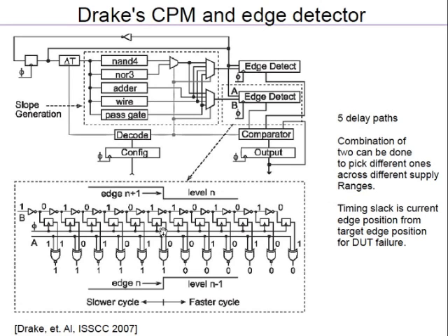In these approaches, your unit of measurement is the delay of an inverter, and these are maybe fan out 2 inverters, because this inverter is going to this inverter plus it's driving some load in the flop. So what is the resolution available with these techniques? About fan out 2. In your 16 nanometer process, maybe 4-5 picoseconds.